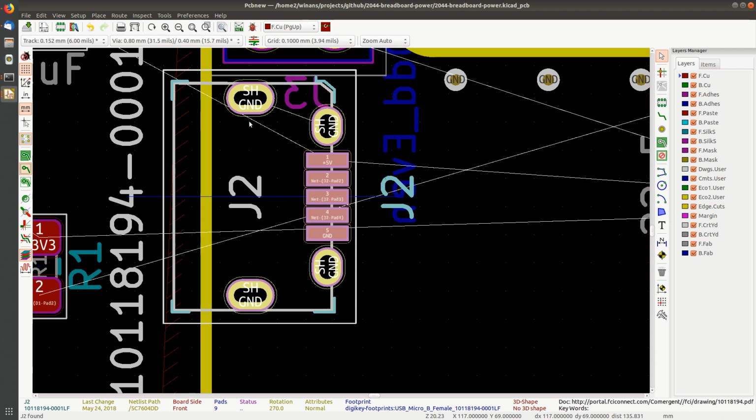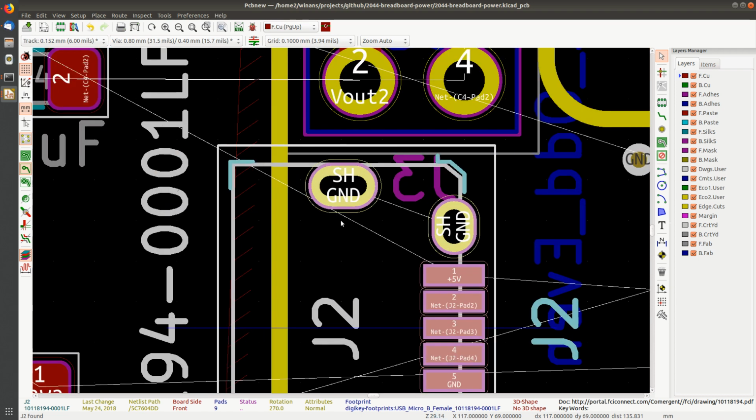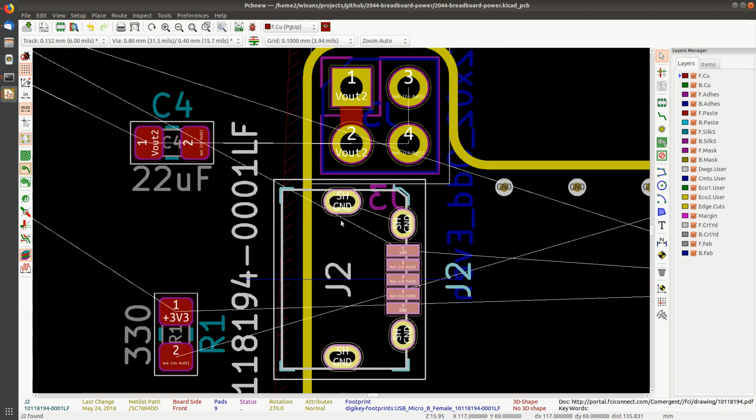So this guy right here is at 117.0. All right. So if I move in tenths over to the left, 9, 8, 7, 6, 5, 4, 3, 2, 1, 0. So we're at 117.0. I'm at 17. Where am I now? 115 and a half. So that's 1.5 millimeters away. The recommendation was 1.45. So this is in a good position.